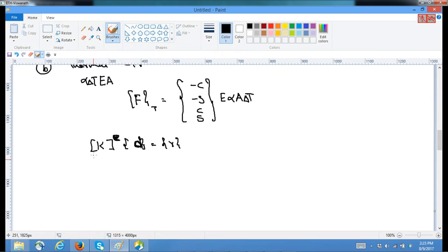But we know that the elemental forces Re come from the R due to gravity, or F due to gravity, plus F due to thermal. In generally interesting members, the expansion would be there, so we need to consider thermal expansion as well as gravity, which will give us the elemental forces.